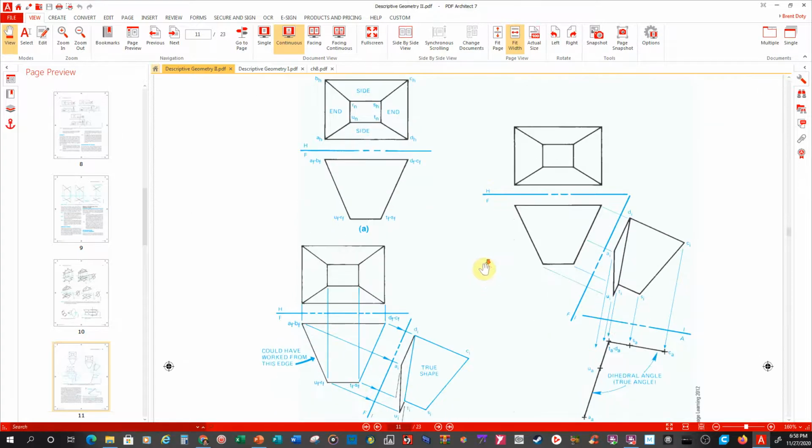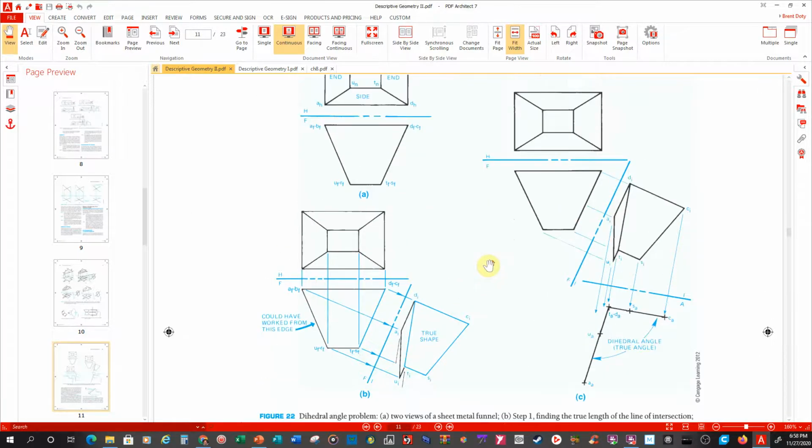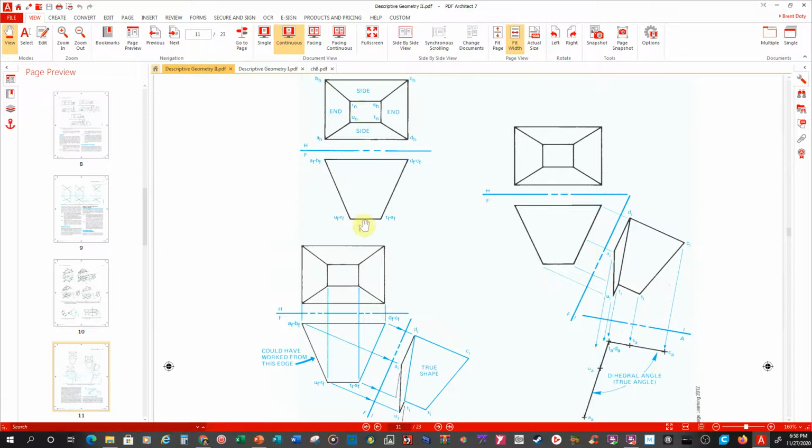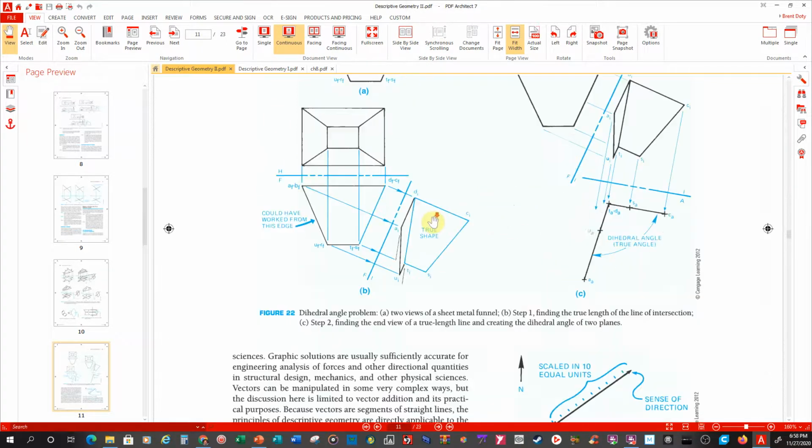Okay, this is a piece of sheet metal, basically. It's converting from this rectangle to this rectangle. How do I figure out how much material I'm going to need? When we create sheet metal drawings in SolidWorks or Inventor, it's doing this unfolding for us, but we could figure it out manually if we wanted to.